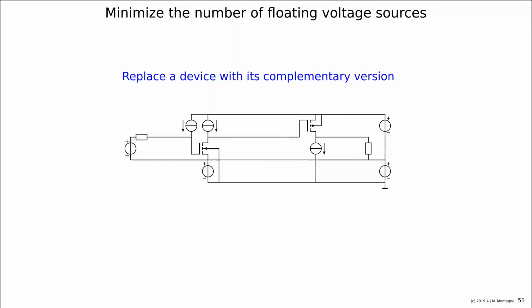But if you swap the device to a P device, things become different. Now there is a path from the plus over VGS of the first transistor through VGS of the second transistor through VDS of the first transistor. And if the output impedance of the first transistor is not infinite, and generally it is not, there is a transfer. The power supply now has become a signal source, which means that generally in this case, you pay a price in terms of the power supply rejection ratio.